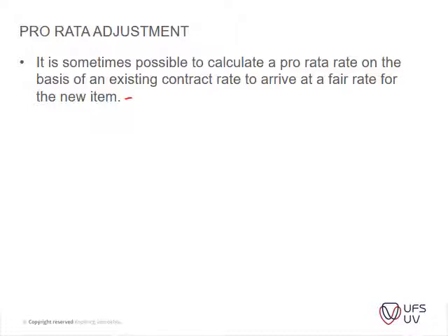The reason for taking this example is that purlins are measured in number in your bill of quantities. But to get to a rate without going and getting quotations, you can very quickly calculate a more or less rate for the purlins.